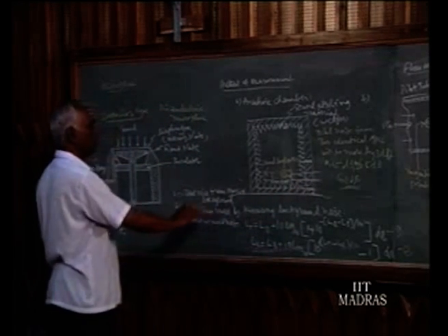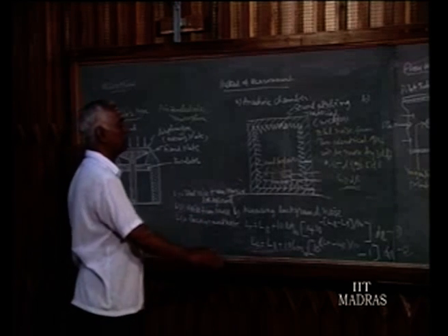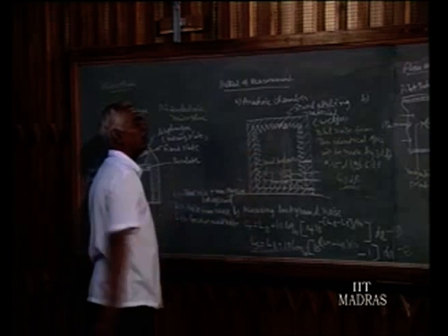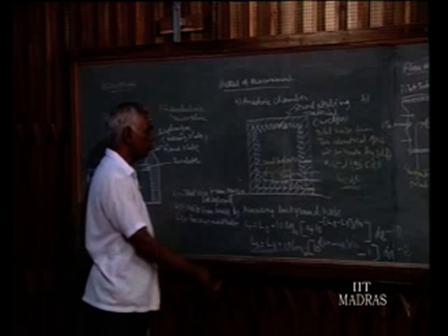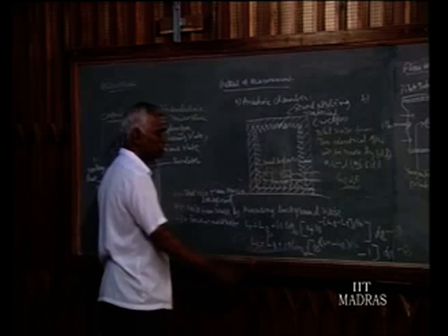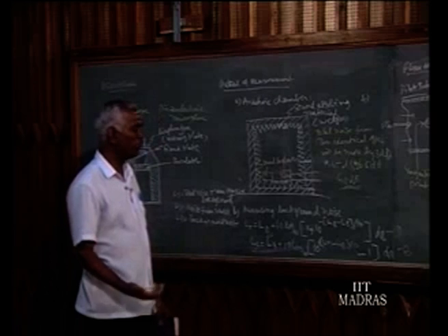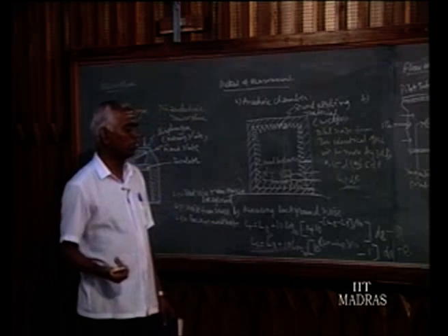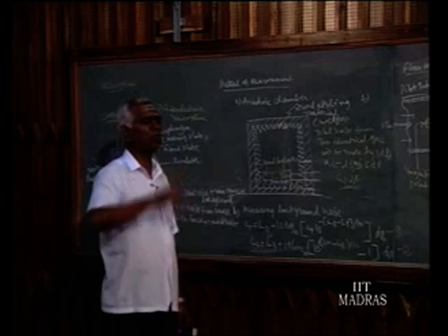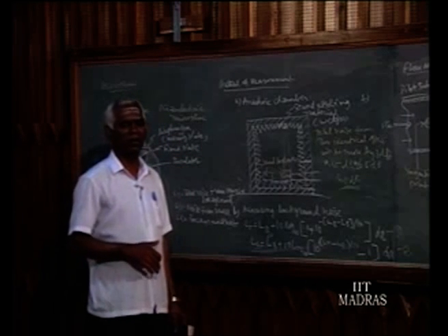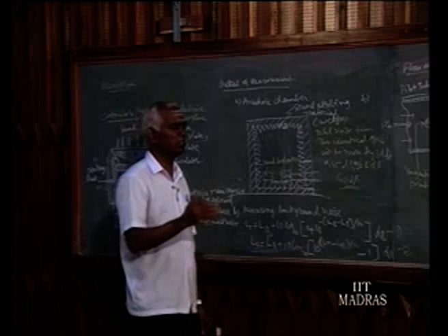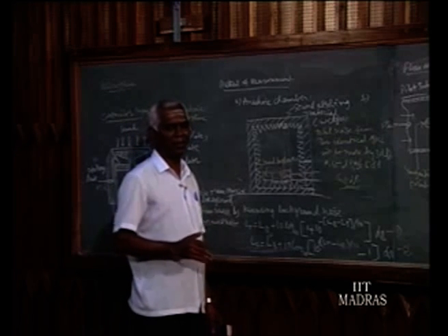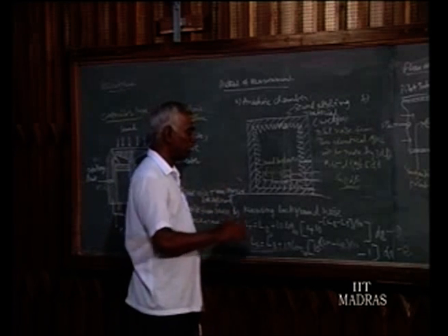That is an easier way of making measurements of noise instead of the anechoic chamber, which is costlier. But you should have control over the background noise, and that is sometimes very tough. That is why in our laboratory when we want to make such noise measurements we come at midnight, so that there will be less noise around, only noise from the birds and the wind may be there, but it may be more or less constant, and then we make measurements.